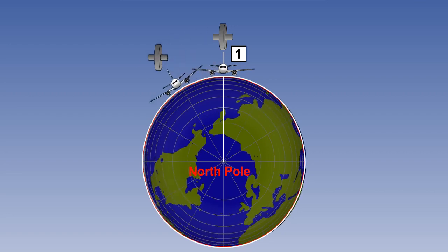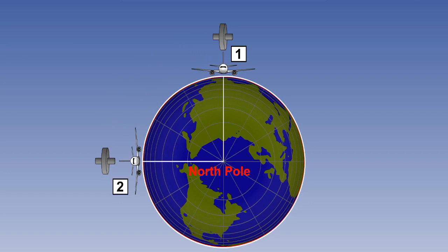The Earth then rotates, taking the aircraft with it, to position 2. The gyro, being rigid in space, has retained its space orientation. The orientation of the aircraft to the gyro has changed by 90 degrees, and the gyro is now indicating 90 degrees of bank. So, at the equator, we get the full 15 degrees per hour of vertical component of Earth rate.